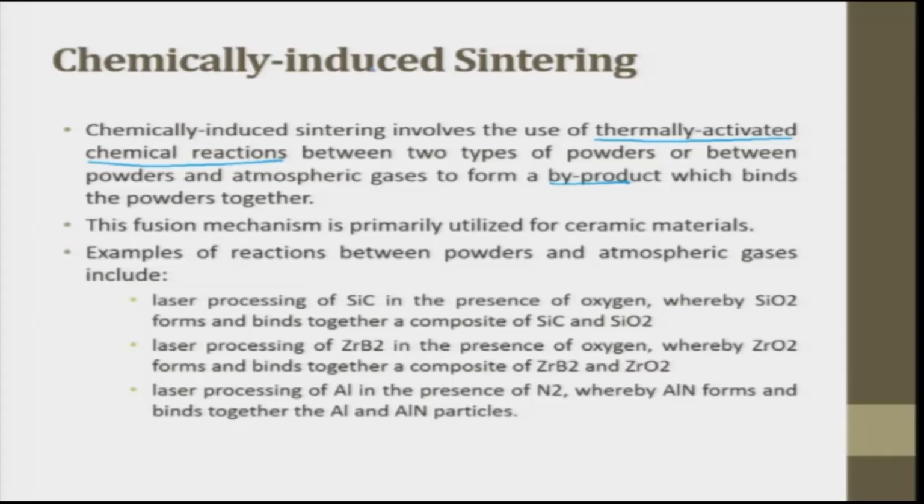Okay. In chemically induced sintering, what we do involves the use of a thermally activated chemical reaction. Here there is a reaction, but in the laddu example there is no reaction. A thermally activated chemical reaction between two types of powders or between the powder and the atmospheric gas forms a byproduct which binds the powder together.